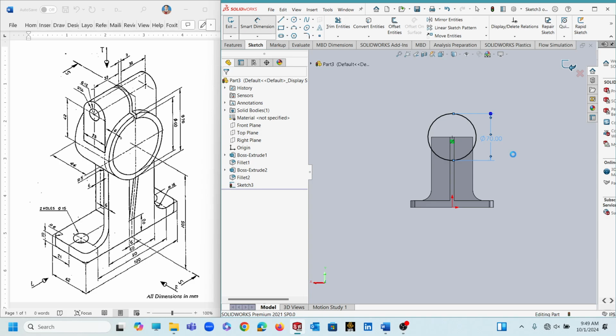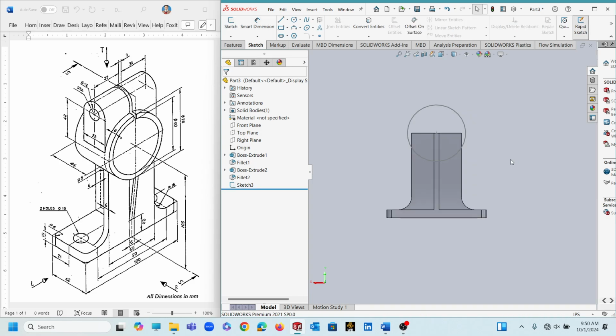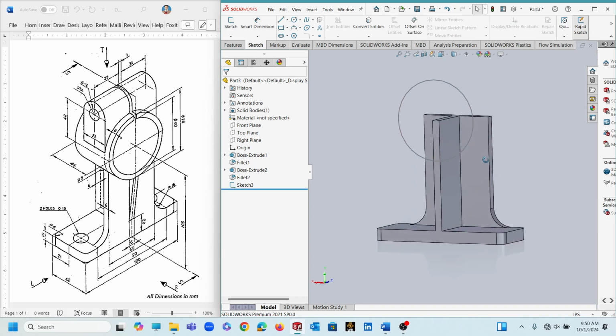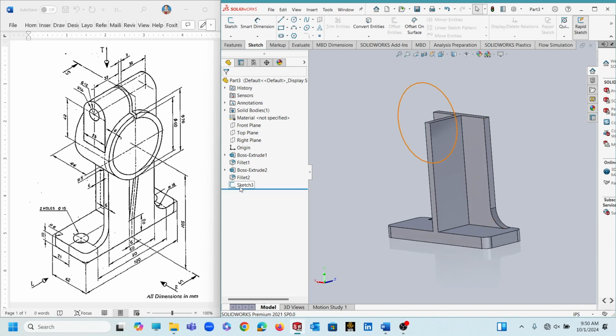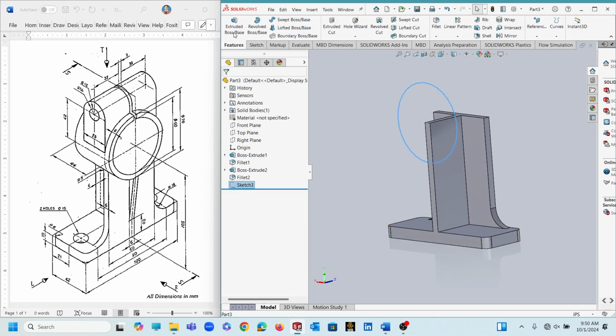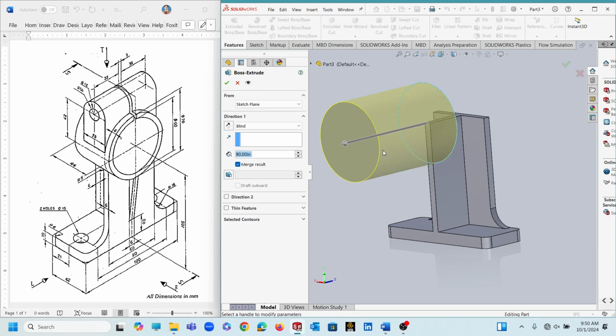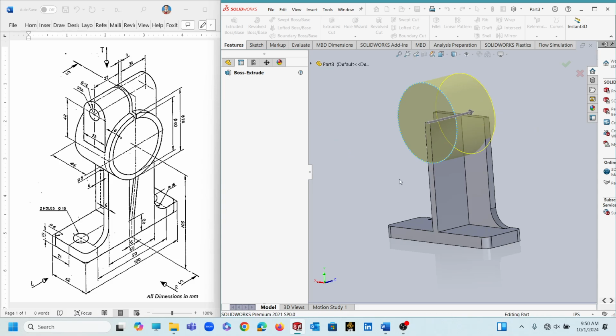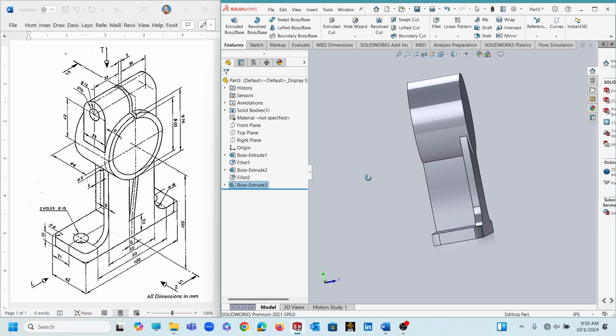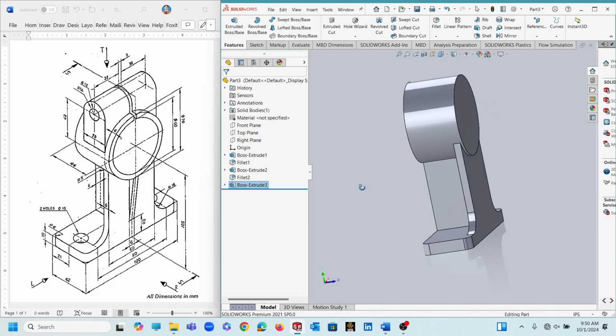This sketch is available on the back side of your part. Here you will choose sketch feature extrude command, and you will say total protrusion or extrusion, it should be of 44 units. So from here you can see your extrusion is slightly more on front side. This is the difference of 2 units that you have from your base width.